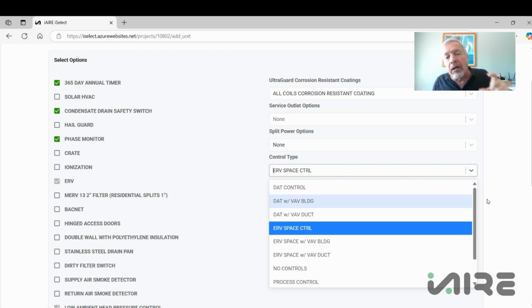Discharge air control, we always, always, always control discharge air, but in discharge air control, we're controlling to what's coming out the end of the unit. And we have a special sensor that gets placed in the duct about 2 feet downstream in the supply duct that is the control point for that. So with discharge air control, you will not get a wall-mounted thermostat or device of any kind, because it's controlling to what's coming out the end of the unit.